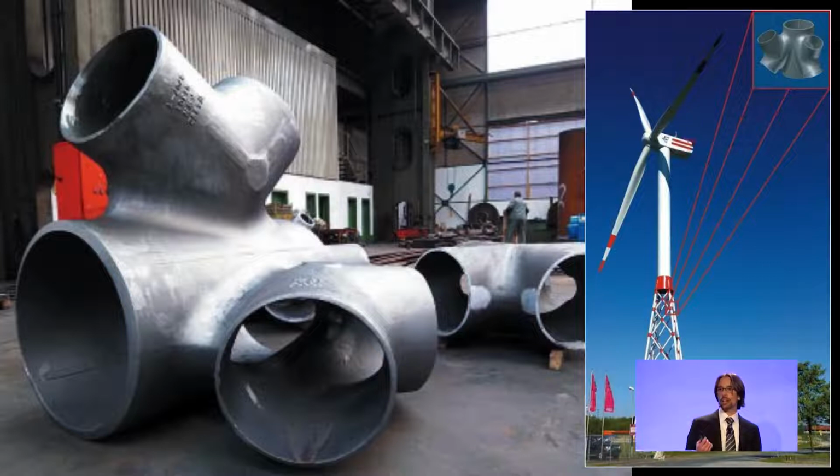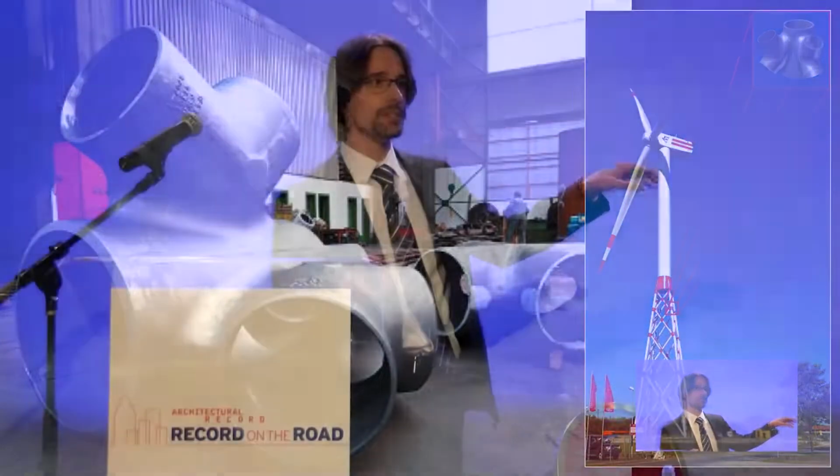The castings are actually enabling that structure to last 10 times longer in service because with casting materials, we can put the material where it ought to be for the flow of forces through those connections, and we can make highly optimized structural forms that can do things that conventional structural steel could never do. We move the welds away from regions of high stress concentration.